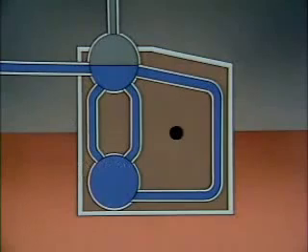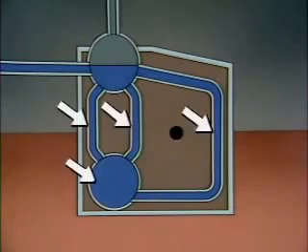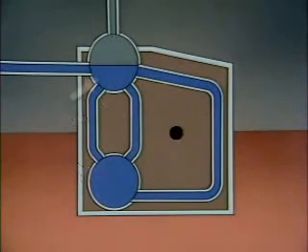Boilers normally have several downcomers. In addition, there's a feed water inlet and a steam outlet. The water tubes in the lower drum are filled with water. The steam drum is only partially filled. There's enough space in the steam drum to allow steam to collect.